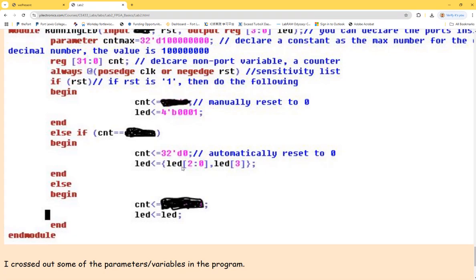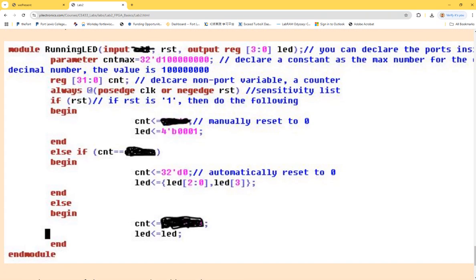Why? It's a module, right? Are you allowed to shift the keywords? No. You have to have an intermediate variable in your testbench. If in the testbench you have to shift something, keep in mind it has to be some intermediate variable. You cannot directly shift the keywords. Just to let you guys know. So here's fine because it's still within the module. I just have the same name as the ones from the FPGA.